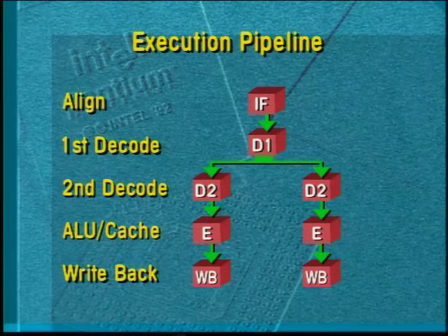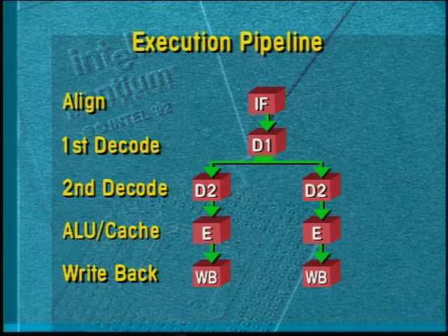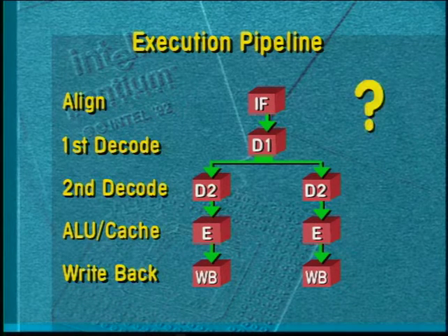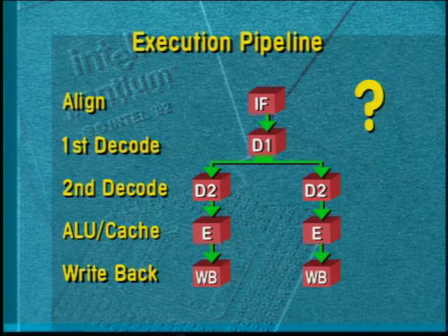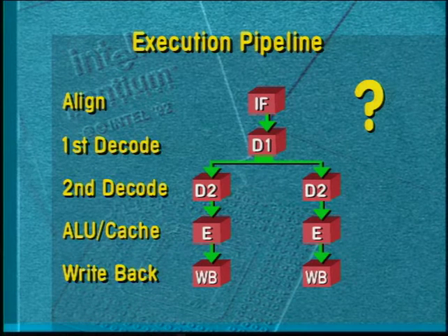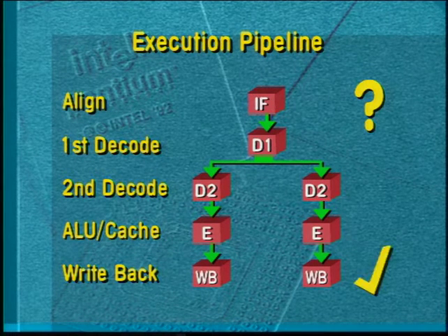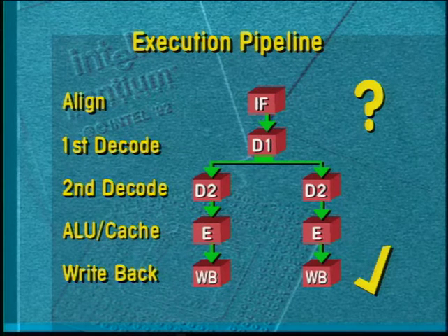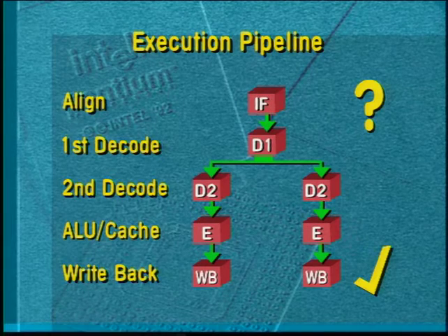One of the most important performance enhancements of the Pentium processor is dynamic branch prediction. The Intel486 processor flushes its pipeline for every taken branch, at a cost of 2 clocks delay. Taken branches amount to 15% to 20% of instructions executed, representing an opportunity for substantial improvement. In the Pentium processor, we cache information about previous branches and use this to predict future branches. The prediction is made at an early stage of the pipeline, and when the prediction is correct, we can execute branches with no delay. All of the branch predictions are verified at the end of the pipeline. If the prediction was incorrect, the pipelines are flushed at a cost of 3 or 4 clocks.